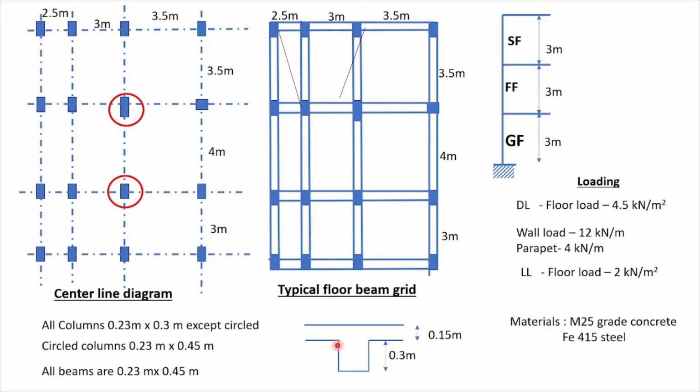So that is the reason there are some standards like 0.23, 0.3, 0.375, 0.45, 0.525. This is generally still in practice. We have the FPS system, with the minimum dimension of the beam starting at 9 inch, 12 inch, 15 inch, 18 inch. There are different sizes in multiples of 3 inches, whether that is the width or the depth.